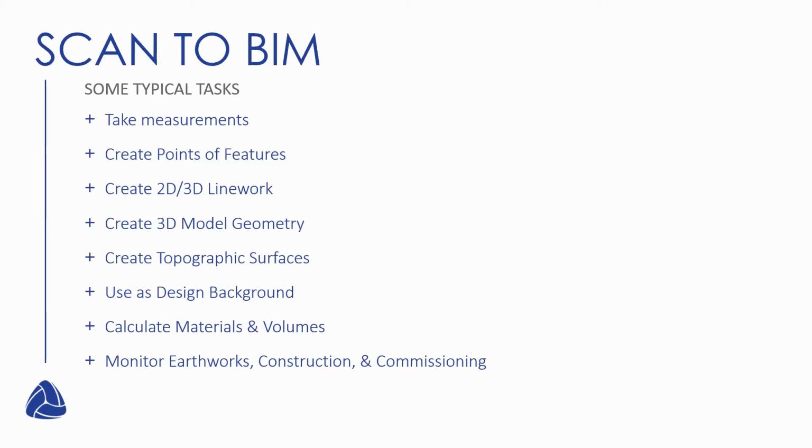Use as a design background, which we have briefly covered. You can also use it to calculate materials and volumes. For example, I like using the example of a stockpile at a mine. By creating a ground surface and then creating a surface for the stockpile itself, you can calculate those material volumes. You can also use it to monitor earthworks, construction, and commissioning.